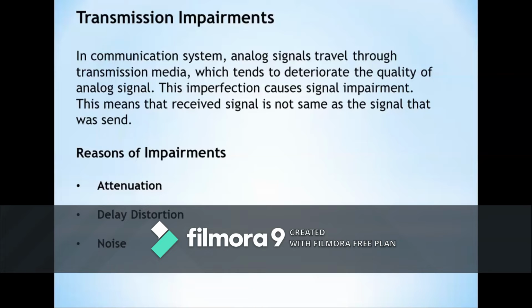Hence, the various frequency components of the signal arrive at the receiver at different instances of time, resulting in a phase shift between the different frequencies. This distorts the signal, and the distortion is called delay distortion. Delay distortion is particularly important for digital data. Due to delay distortion, a digital pulse transmitted over the medium tends to spread out, causing inter-symbol interference.